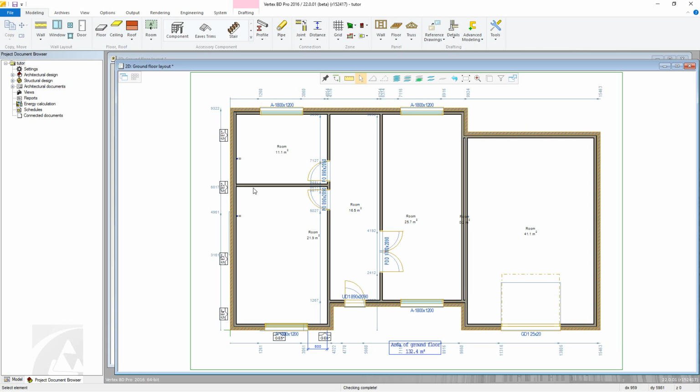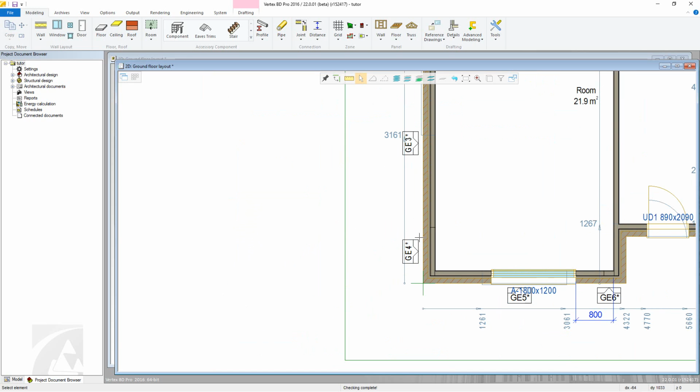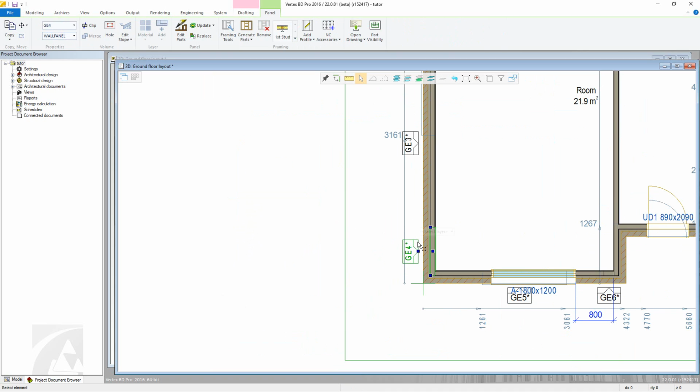When panelizing, only the breaks themselves are generated, not the frame, which gives us an opportunity to amend the panel layout before generating the framing. With the new version, panels can be easily selected by clicking the panel label. Panels can then be easily resized by clicking the grip points at each end.